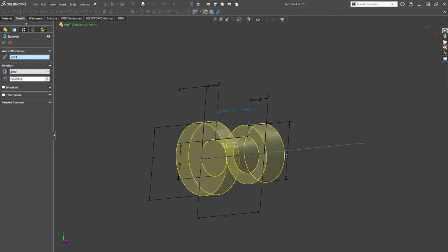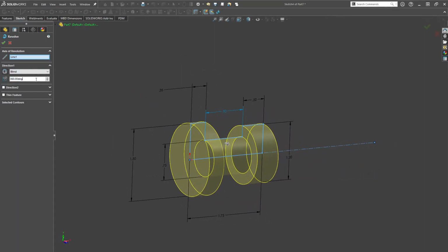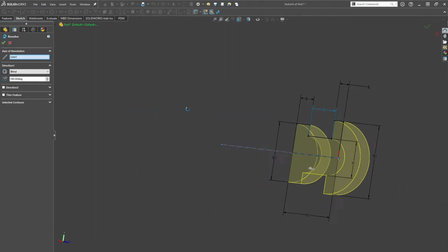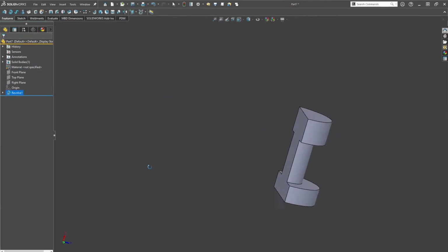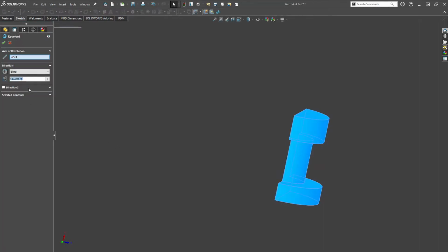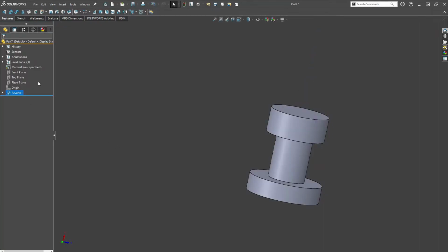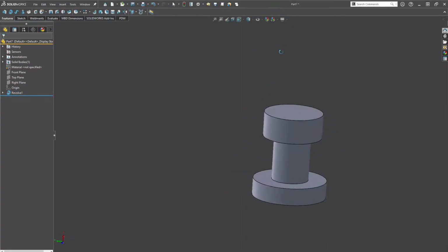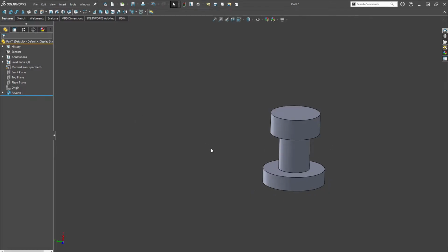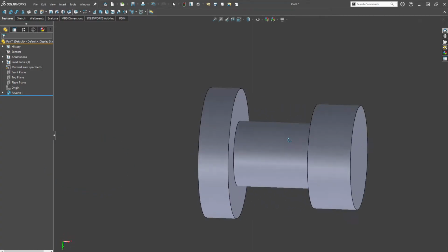A quick note, in case you're making something that isn't actually a full circle, you can tell it to revolve only a certain amount of degrees. So you can make, like, a half pawn, whatever you'd like to do. But in our case, and I think in most cases, you're probably going to be revolving 360 degrees. So here's that pawn again, and we could do the fillet thing again, a fillet here and here to make the body and a fillet on the top, but that's not necessarily the best way, especially for the body, because there's not a lot of control.